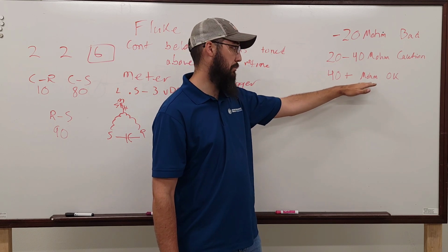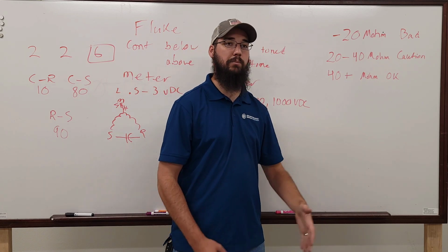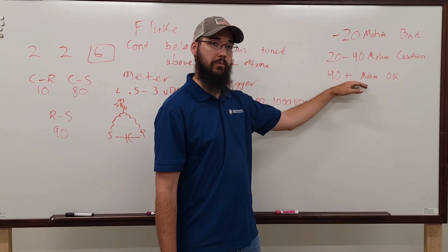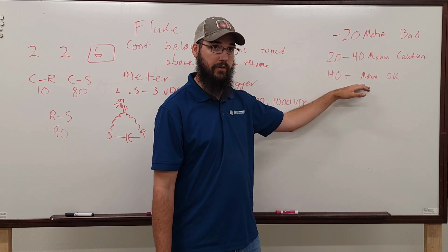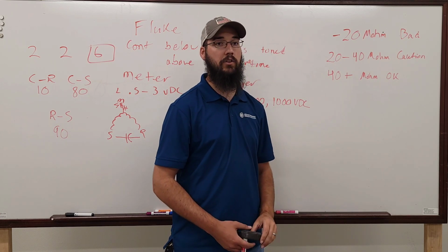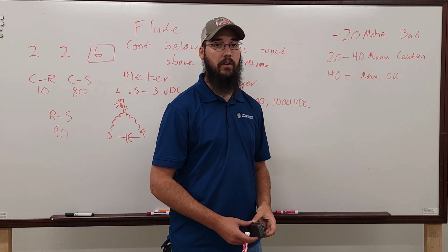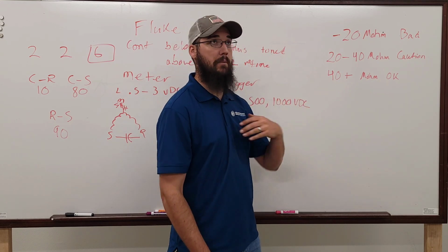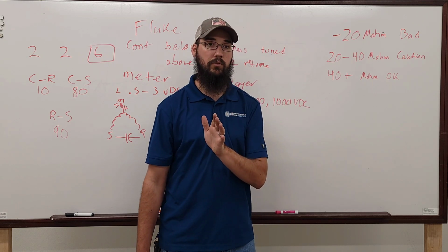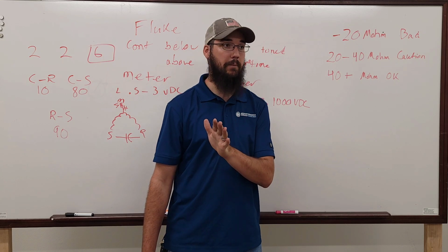Most of the time, electrical failure, right? Just like we use vibration analysis to predict mechanical failure on bearings, we can use megohms to predict electrical failure. Between the two, you could probably tell a customer years in advance a motor is going to fail before it ever does. Because what'll happen is, my mega goes up to 2 trillion ohms. No, sorry, 2 billion ohms is what mine caps out at.